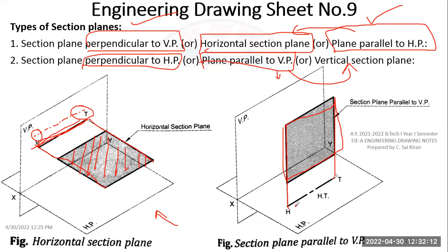From this point, I have to draw this cutting line: again line, dot, line, dot, with the darker HB pencil, and then the lighter pencil, again line, dot, line. I have to write HT, and this is my hatched portion. So here I have to hatch. This hatching will be on the VP. If I project this, the hatch will be on VP if it is cutting like this.